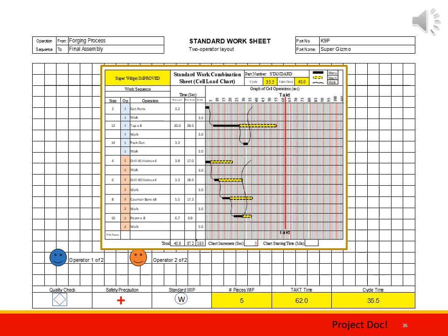Some of these numbers you guys are going to have to make up because you don't have walk times. You're going to look at your cell layout and decide how long it's going to take to walk, and that's the number you're going to use. Your automation class, if there's an automation piece of equipment, you know what the cycle time is for the automation equipment. But if it's a manual operation, this is the whole table time thing we've talked about. You'll have to construct your table time to manage that.